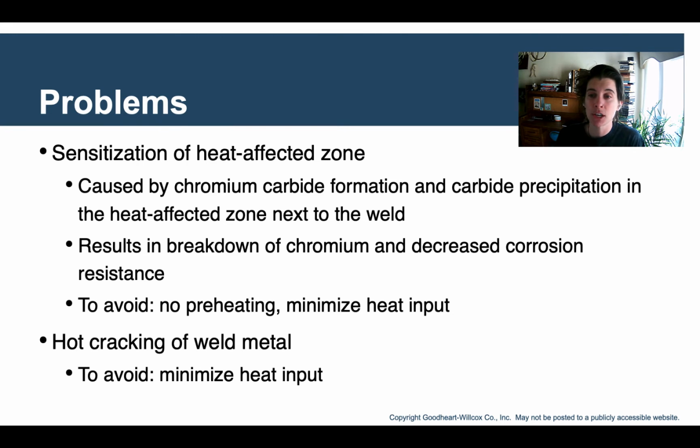The sensitization is caused by the chromium carbide formation and carbide precipitation in the heat affected zone next to the weld. So it's basically inconsistencies in that heat affected zone area, which can cause cracking there. This look of sugaring, you'll see it looks like burnt. You can see that there's a problem with it, and that the end result there is a breakdown of the chromium, decreased corrosion resistance in the end.